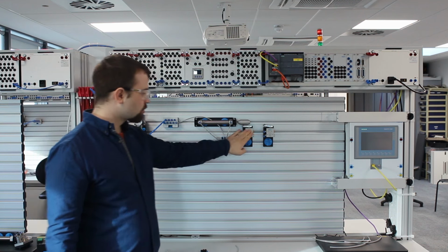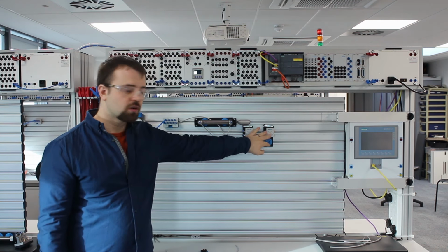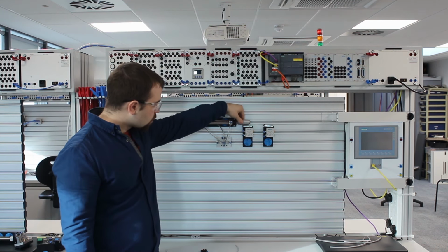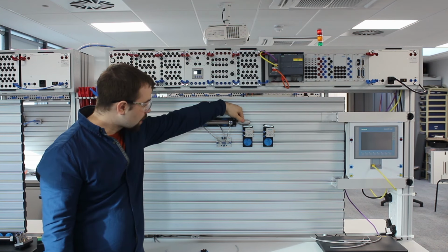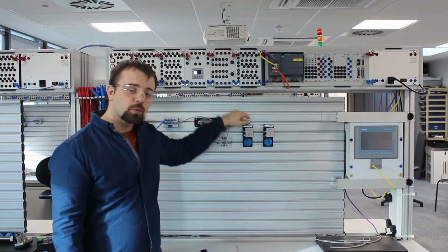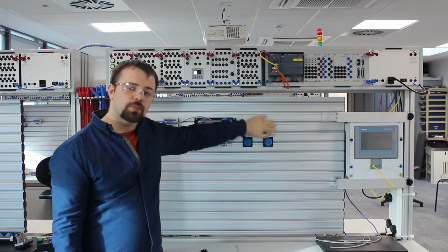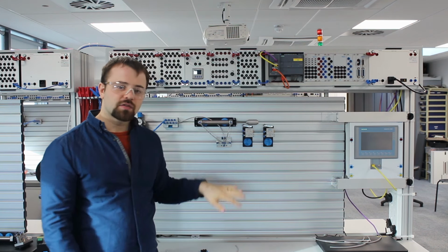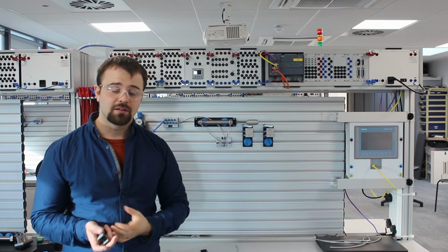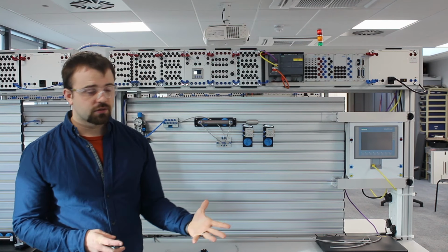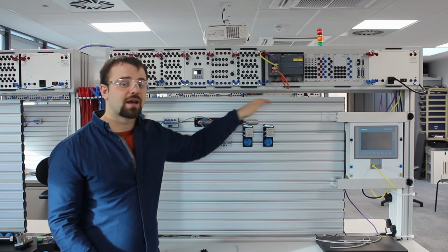Okay, so I've attached the two roller switches to the board. This one is okay because, as you can see, the cylinder comes back and presses into it. This one will work, but really it should be the other way up. I'm leaving it down here for the moment just because it's going to make the circuit a lot easier for us to see. But if you are building this circuit yourself, please put this upside down to avoid wear and tear.